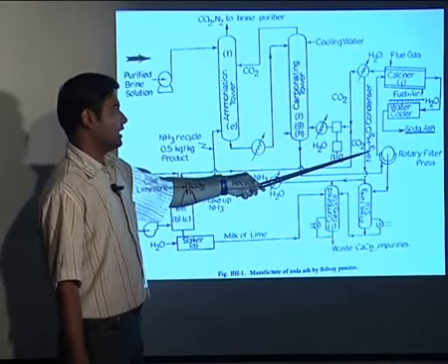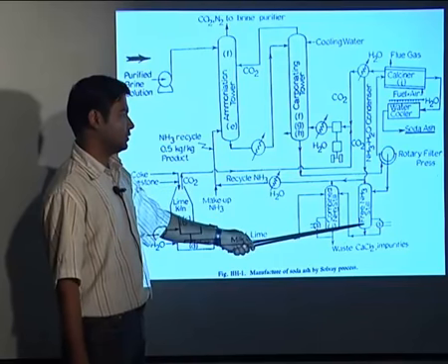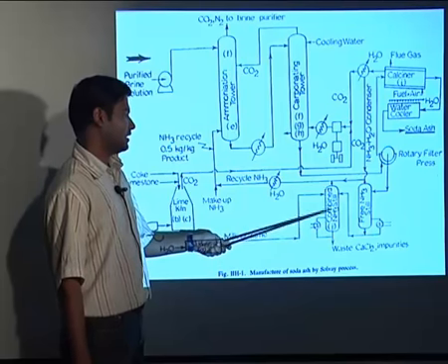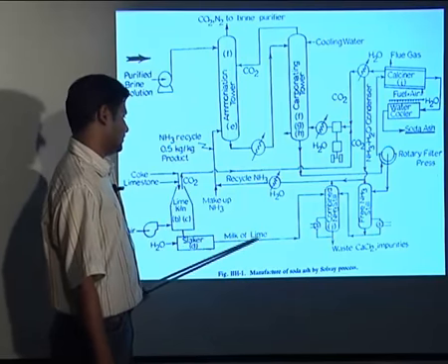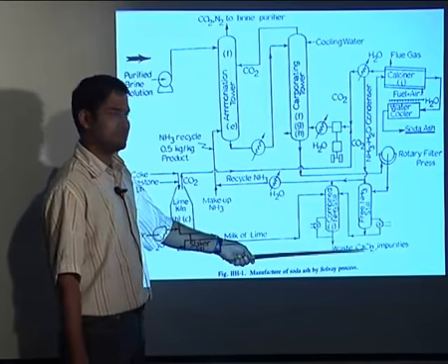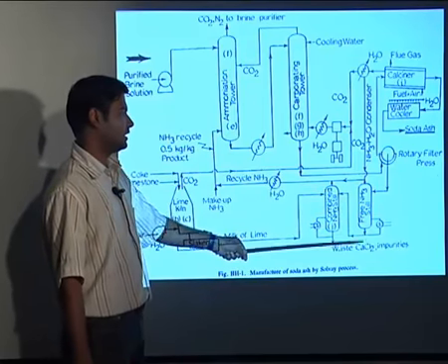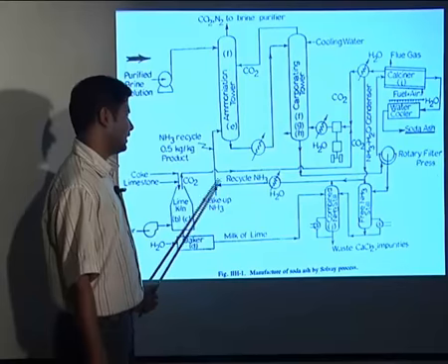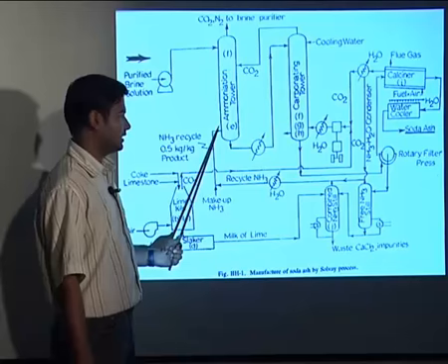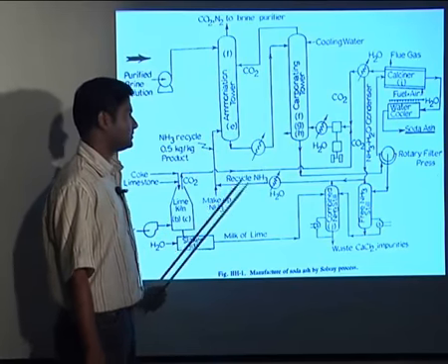And whatever the ammonia and the water which we are getting over here, so here you can see it is heated up to recover the ammonia. Also whatever the combined ammonia here, that we are recovering. And then here we are sending the milk of lime to recover the waste such as the CaCl2 or other impurities. So this will be recovered from here and the ammonia will be recovered from here, and we can recycle whatever the ammonia which is recovered over here, or if the ammonia is lost over here, we can have the makeup ammonia.